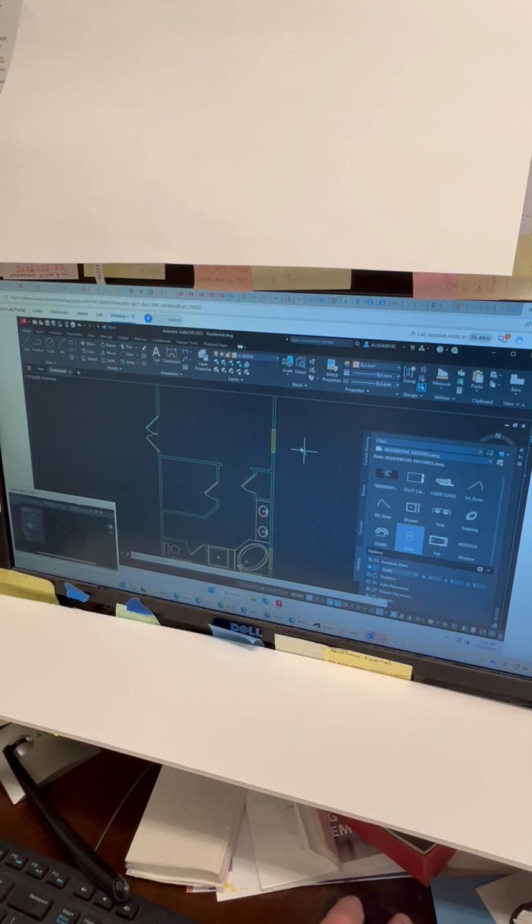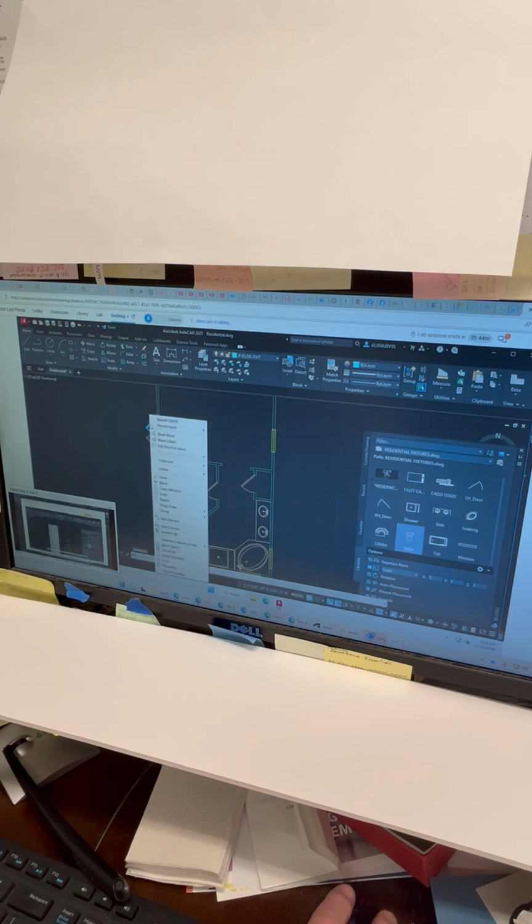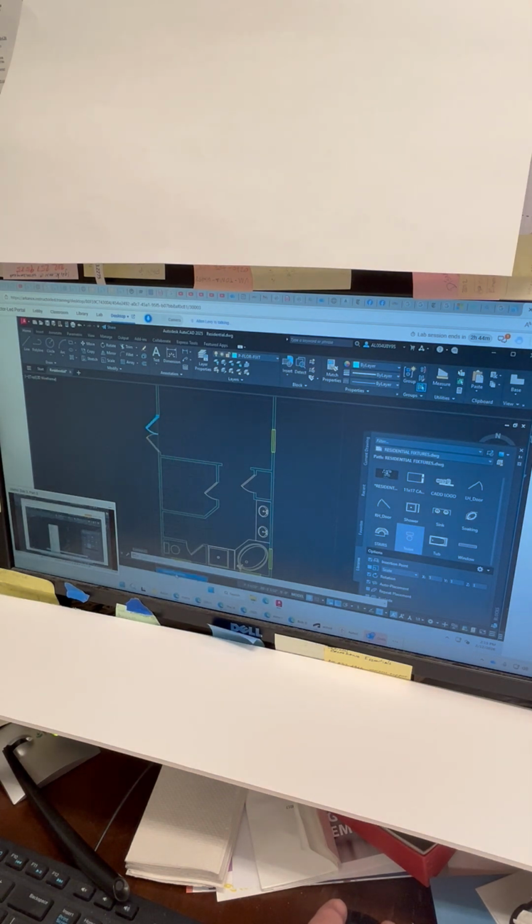I'm looking at your drawing here, and here's what I can maybe say. I'm not sure, but I'm going to try to recreate what happened there. The layer says P floor fixture. Apparently something happened where all of your plumbing fixtures are supposed to be on that layer, and it got switched over to the door layer. Here, I'm going to get rid of this thing for you. You don't need this to confuse matters.